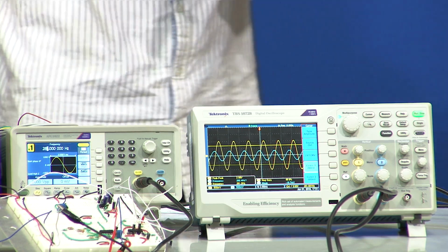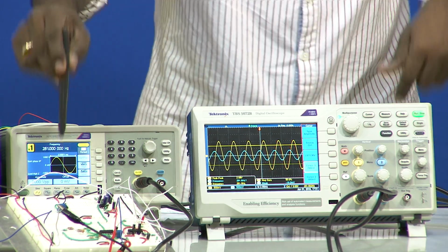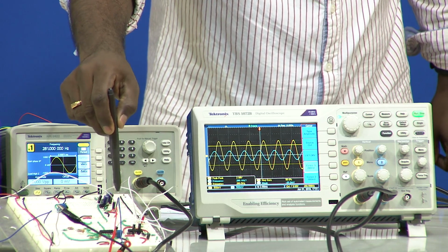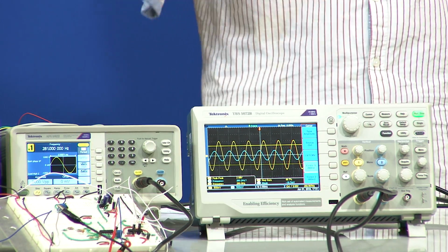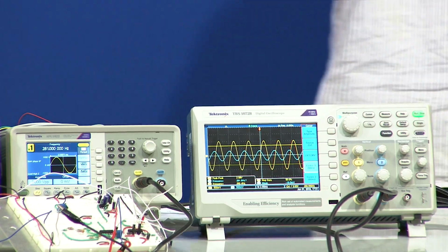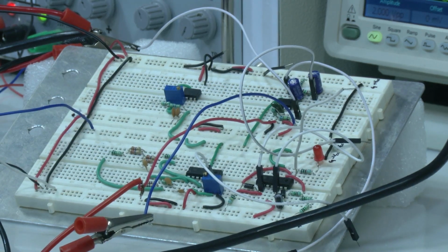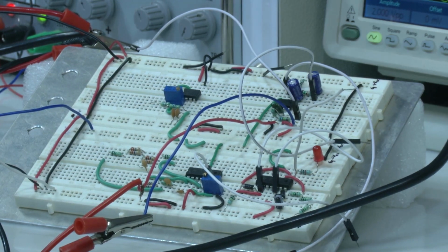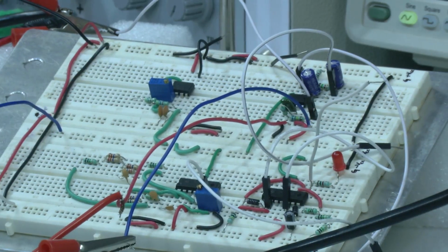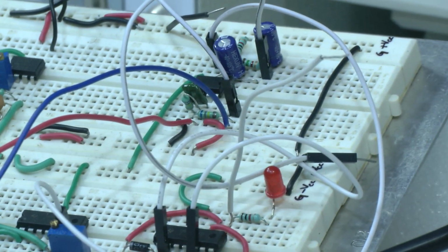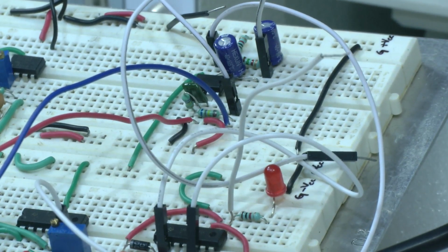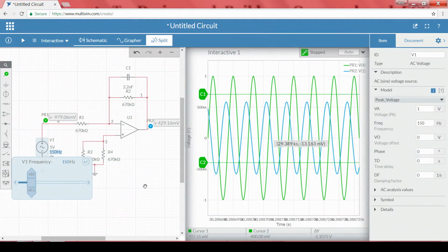So this particular operational amplifier circuit, we will use for our low pass filter circuit, so that the power line interference due to odd multiples will be completely removed by using this low pass filter. Now what next? We also require a notch filter as well as a high pass filter. Now we will look into the high pass filter circuit, right. So when we go to the presentation,